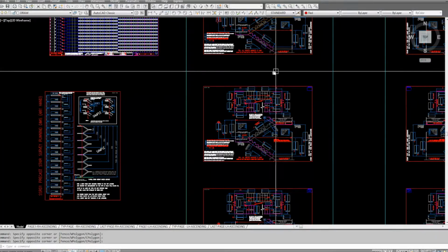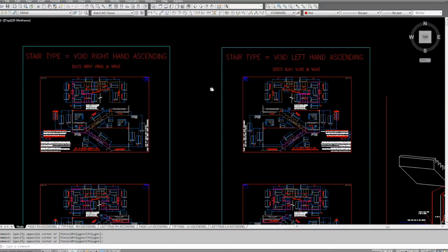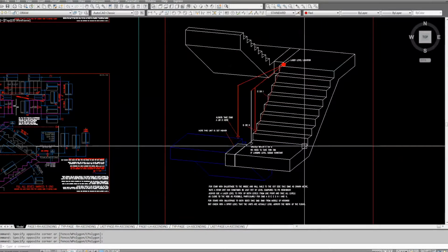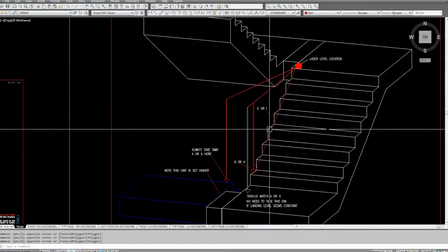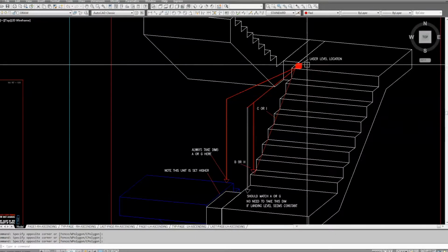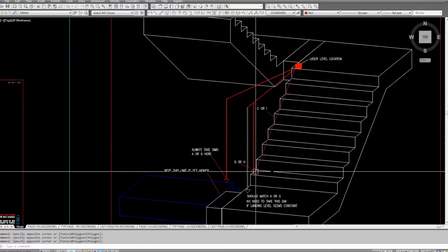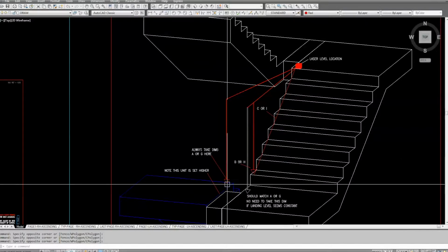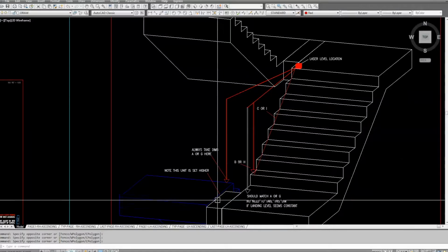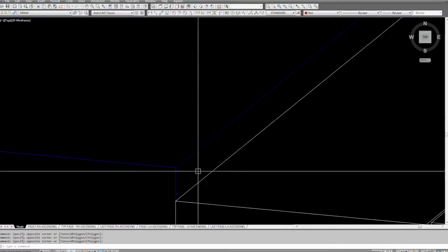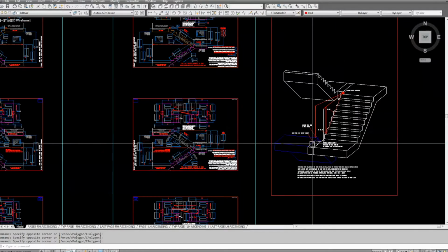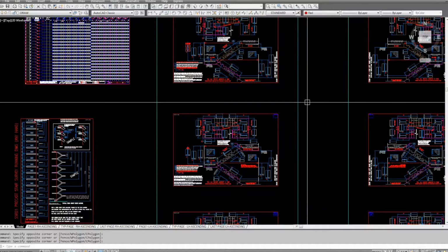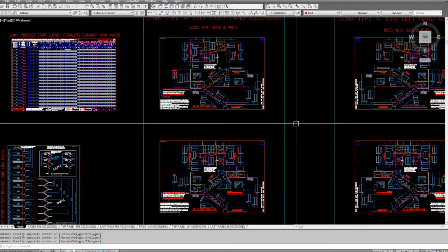So you've got your right hand stair, and I've got a left hand ascending stair. That little sketch there just shows how you should set your laser up. So you measure down to that dimension, you don't measure that one, you cast over and you measure to that one, and you ignore that just in case you've got this scenario here where you've got a little step in your landing. You wouldn't believe how badly installed some stairs are. Well, even cast, some really badly cast stairs.